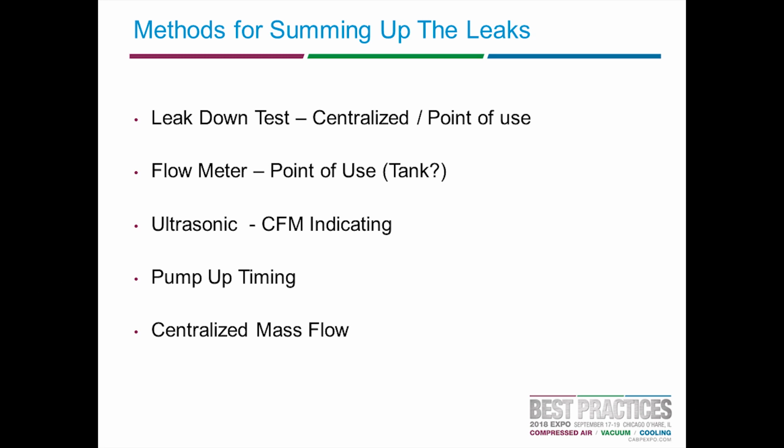Then there's ultrasonic. The more expensive meters, starting about $4,000 and up, can convert the dBA rating to a CFM value. I don't claim it to be very accurate, but it can be a way of putting a value on each of your compressed air leaks.